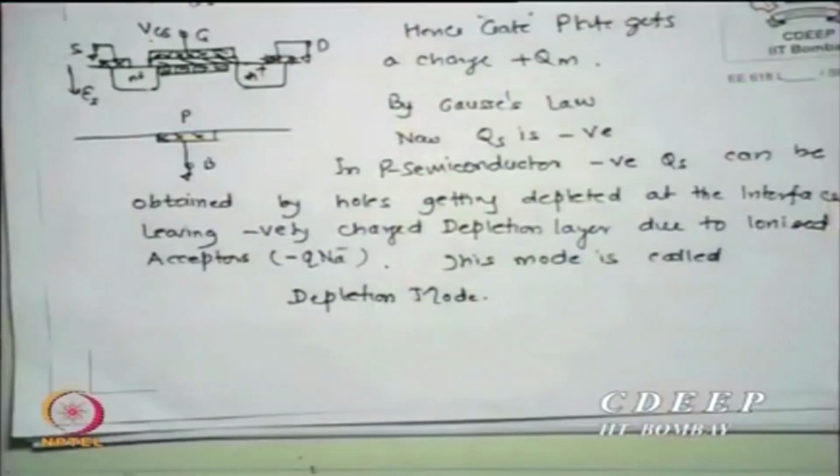That is why Na is constant, so many holes can be given. If the law of mass action has to agree every time, since thermodynamics cannot be violated in thermal equilibrium, then electrons and holes are going to be created everywhere. Even when VGS was smaller and positive, there were electron-hole pairs in the depletion layer, and here also there were electron-hole pairs.